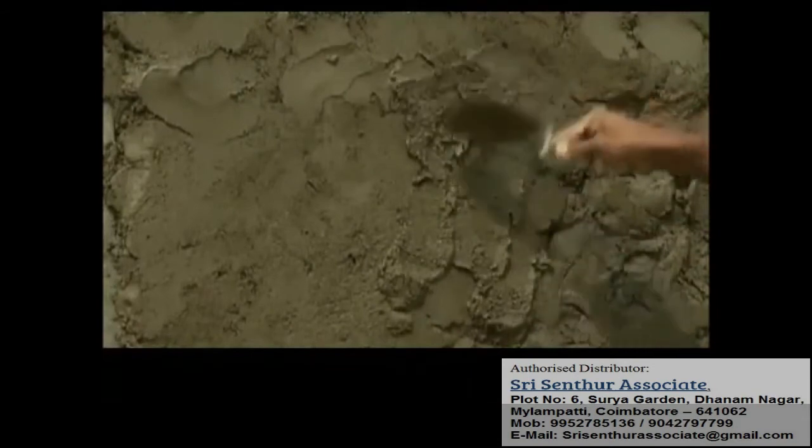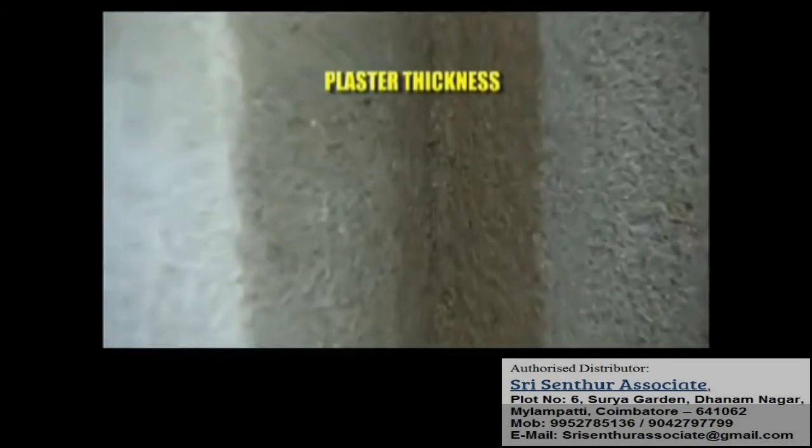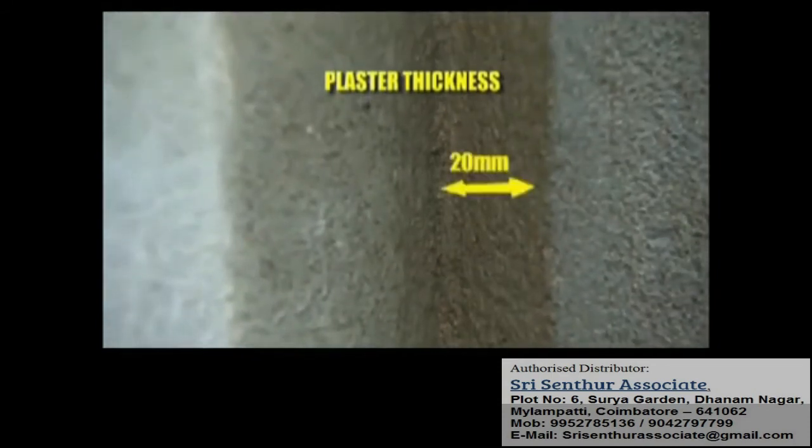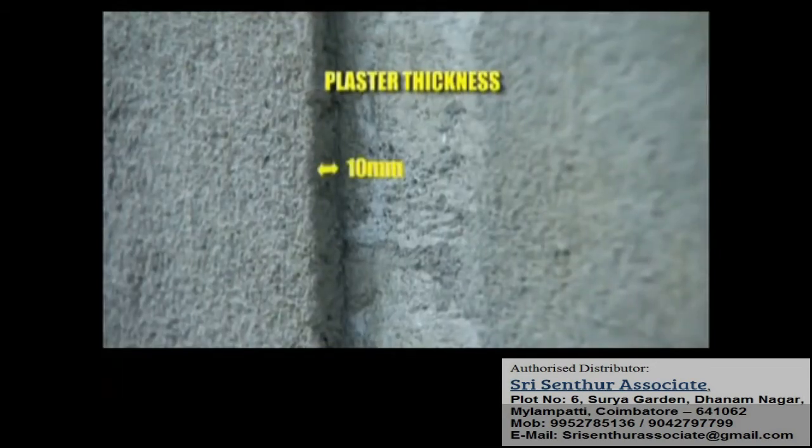The plaster for red clay brick walls becomes thick, as the mason keeps adding thick mortar to the uneven wall to give a smooth finish. Eventually, it is 20 mm thick, whereas the plaster for blocks is about 10 mm only.